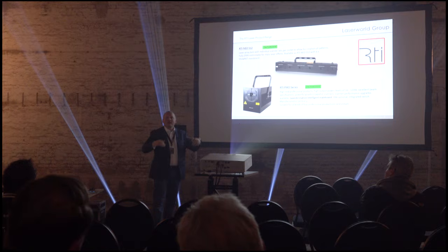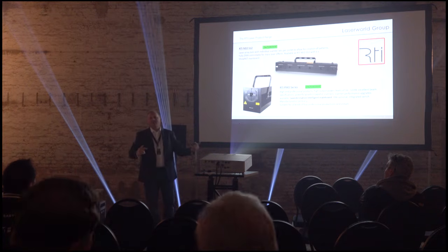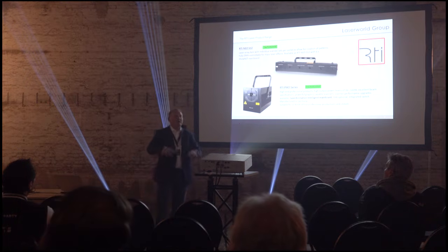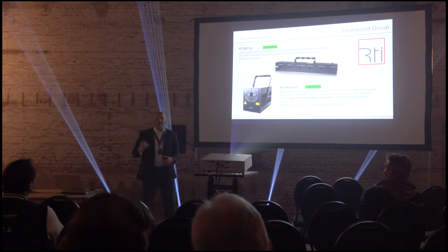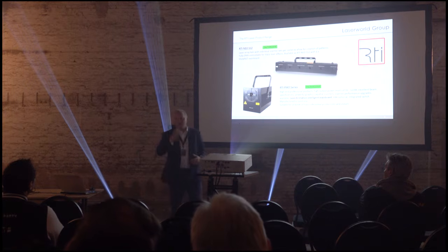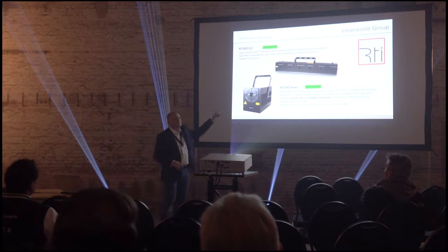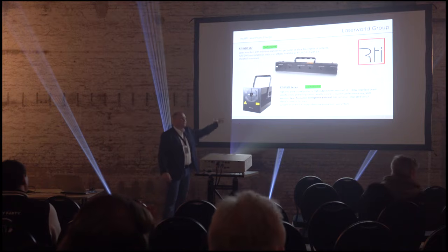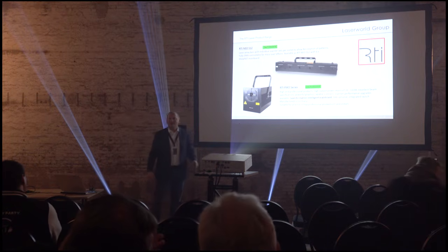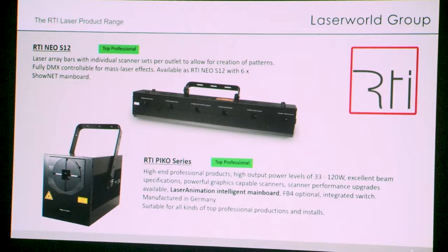because the settings are inside the mainboard and it's not DMX controlling it. The safety is in the main board. So even if you hit full on your console, it cannot get out of that zone. Even if you have a DMX glitch, it cannot get out of that zone because it's integrated into the main board. And that is a crucial feature of the ShowNET mainboard, and it's essential on this product because that makes this product so easy to use on a professional production site for festivals and all this, because the lighting designer can set up safety in the blink of an eye for thousands of lasers at once if he wants to.